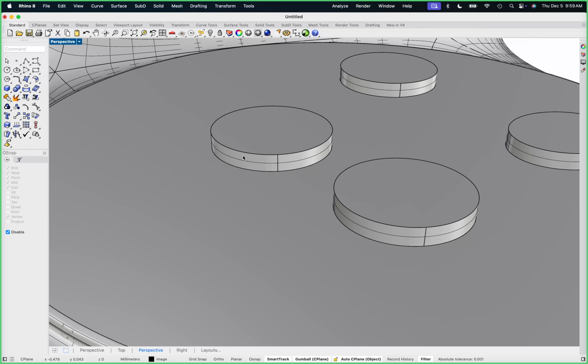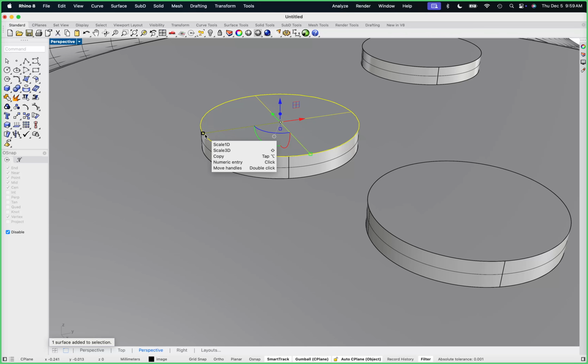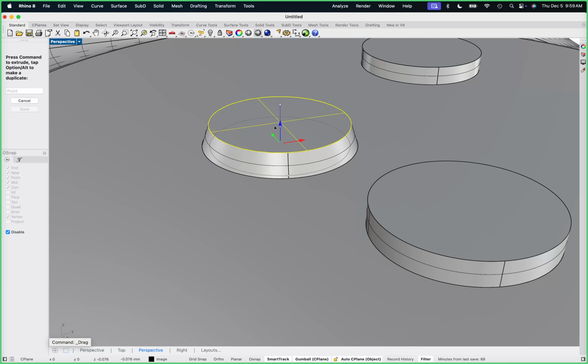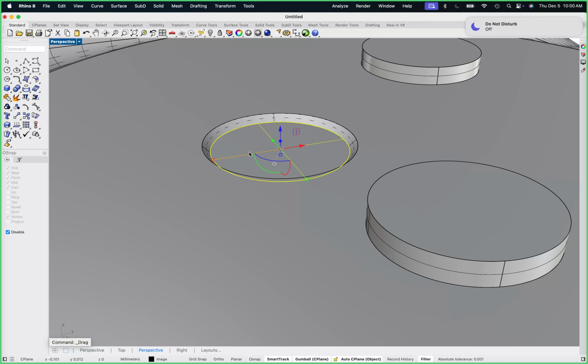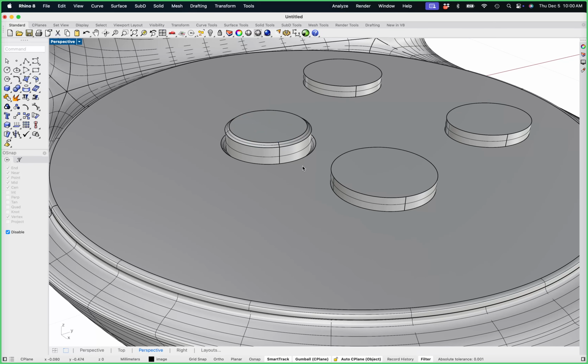Say for instance, if I wanted to do some bezeling or something, I'm going to Shift-Control-Click, Shift-Drag to make this in a little bit, and I'm actually going to drop this in instead of out, and you see that it's created a little bezel. Now I can drag this straight up. I can drag this up again, and then I can shift drag to put a little fillet or a little chamfer on that button. Zero modeling tools, that's all in the gumball.